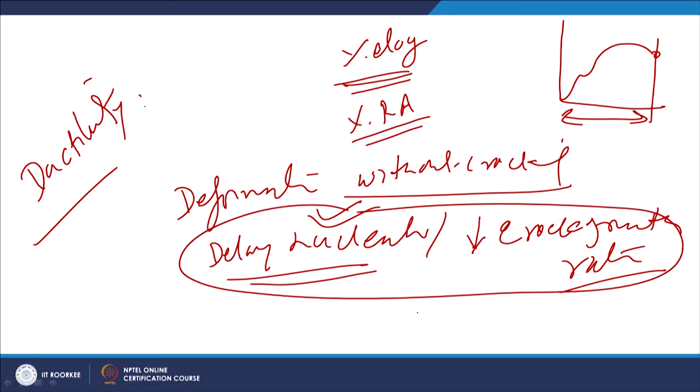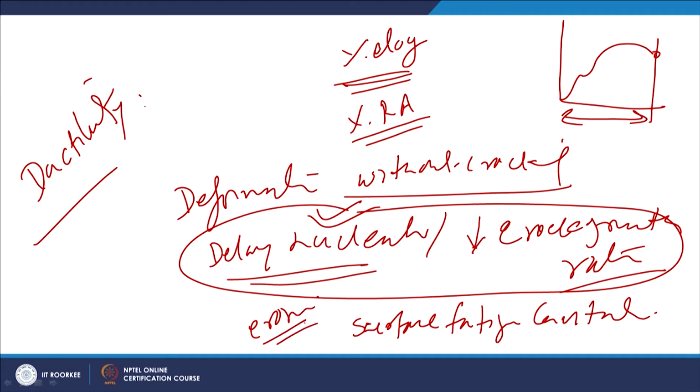delayed. So, under the wear conditions like surface fatigue, cavitation and erosive wear, the ductility really plays a good role, because in these wear mechanisms, the nucleation of the crack followed by their growth, eventually leads to the removal of the material in the form of fine chips. All that is delayed if the material has good ductility.